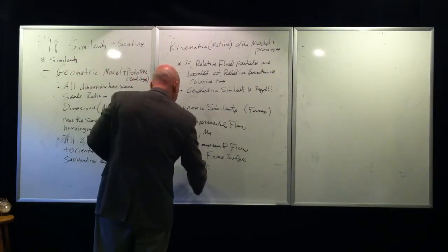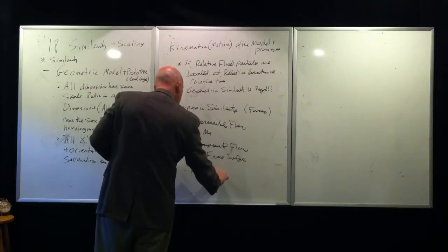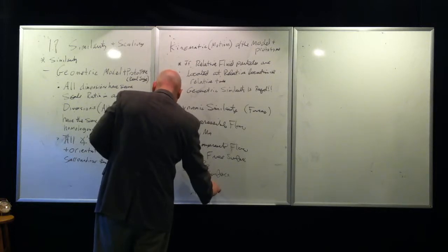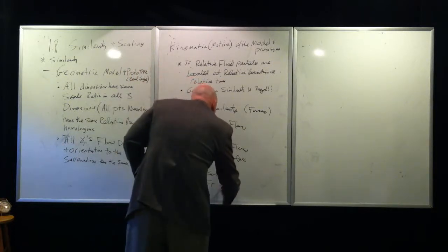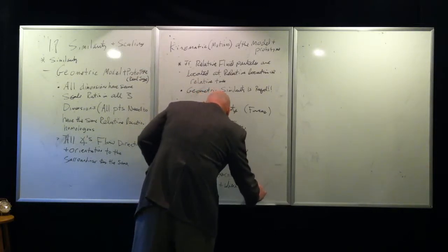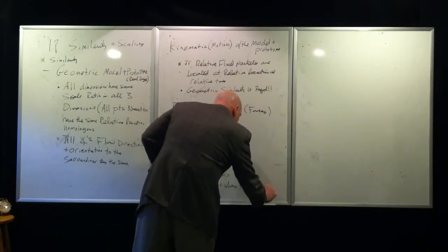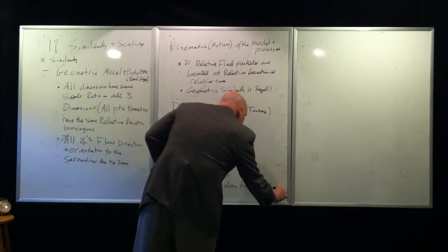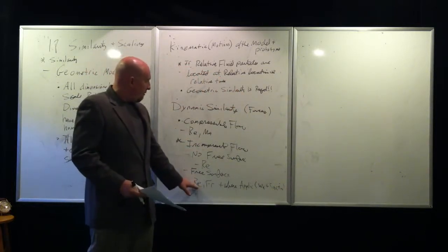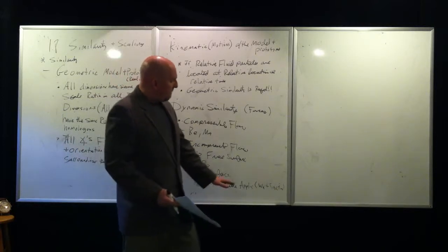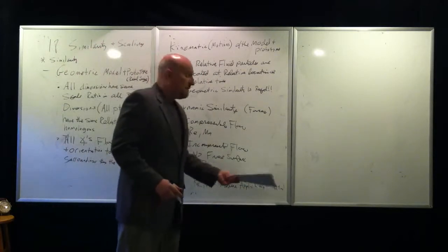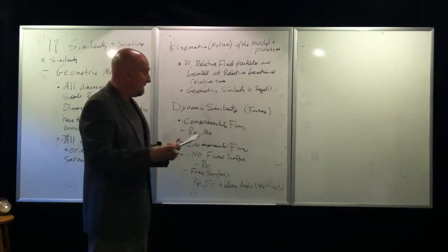If you have a free surface, and it's incompressible, Reynolds number, Froude number, and where applicable, Weber number and cavitation. So the demonstration where we had the mixer, you'd have to have cavitation taken into account.